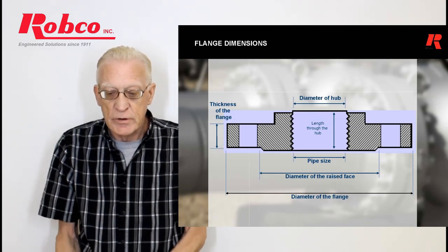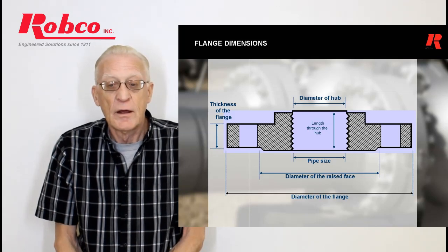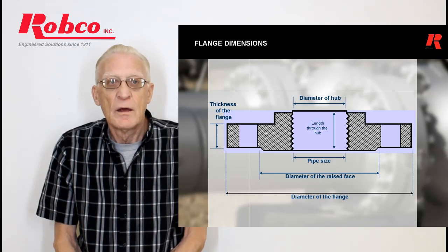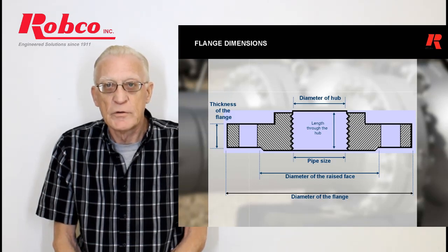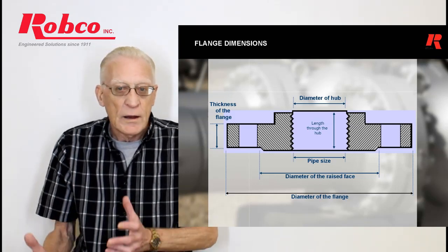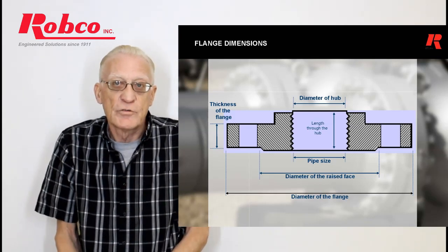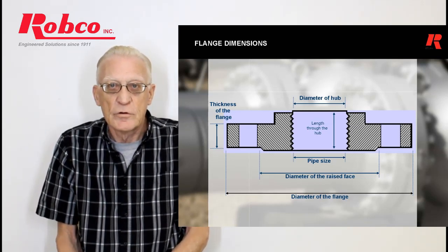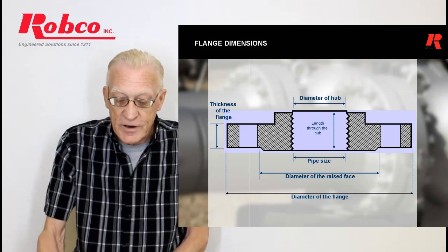Again, the specification used to be that a 4-inch pipe had a 4-inch ID gasket. Now it's 4 5/8. That was designed to ensure that we don't get penetration into the line. The tolerances between the bolts and the bolt holes will allow, in a horizontal line for example, the gasket to drop down and protrude into the line and create all kinds of turbulence, or break off pieces of gasket, and you find it in your Coca-Cola later, something to that effect.